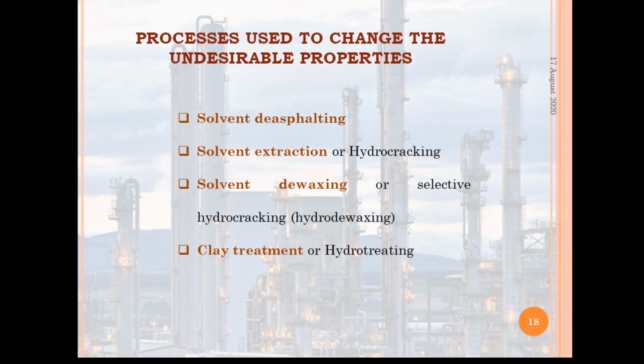Then, mainly in the vacuum column there are demister pads to remove the mist, and we are using structured packing so that we can increase the superficial area, providing mass transfer and heat transfer.